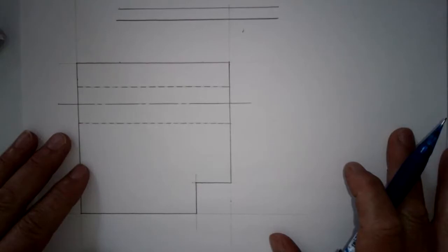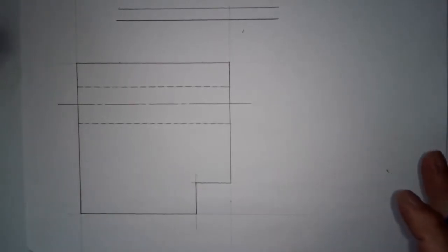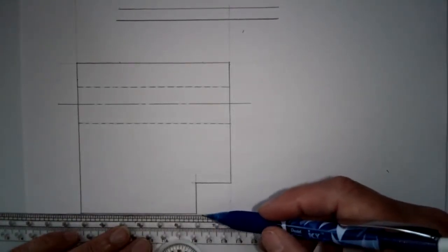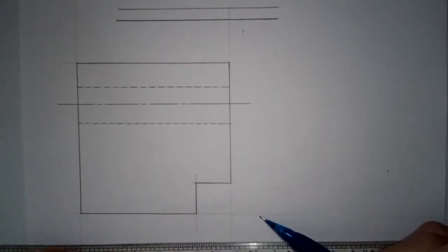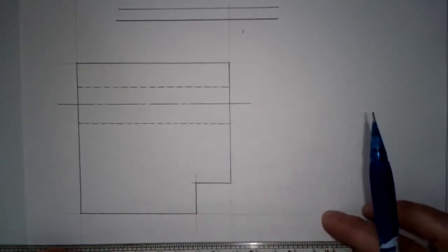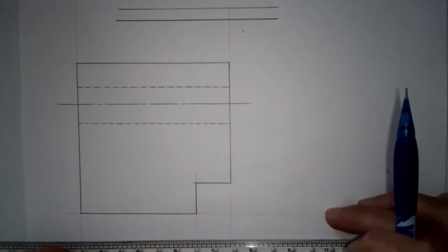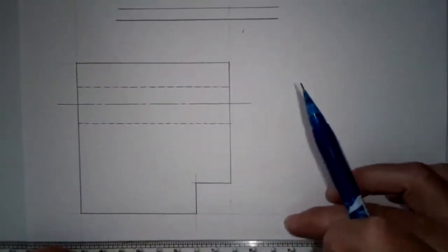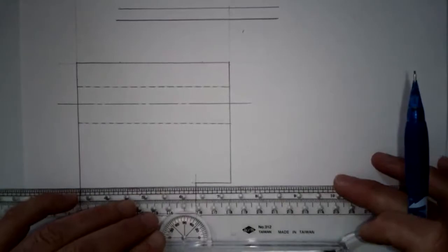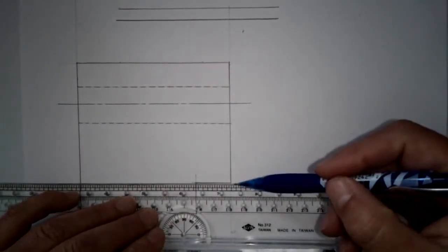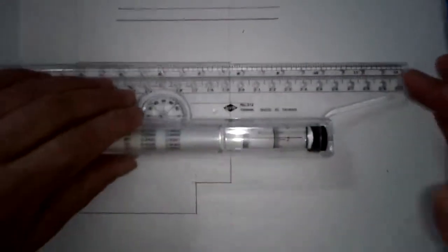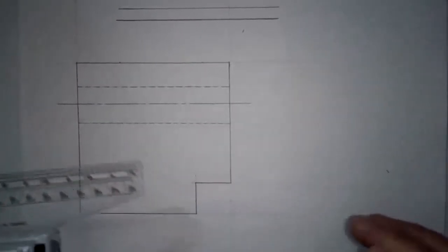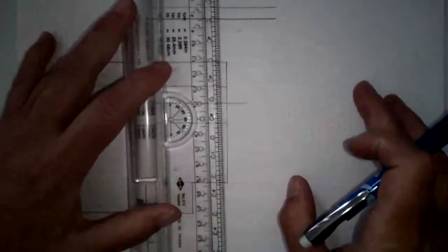So now we've got a center line and two hidden lines that are representing the features on this view, and let's pretend we want to add some dimensions. Dimensions are also a thin line, but I'm also going to start off with construction lines, and I actually have a pretty good construction line there. This is where that construction line came in handy for me in more than one situation. It helped me locate the object lines. I'm also going to use it to locate my extension lines, but this one needs to be extended. And I need to extend this one over here too.